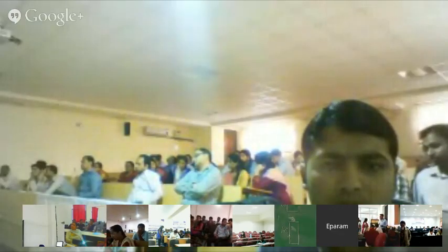So this architecture of the memory is very important: how many should be X and Y. It depends on this. And the earlier one, 256 cross 1, will take around 3 to 4 times more power than if you have X and Y the same.